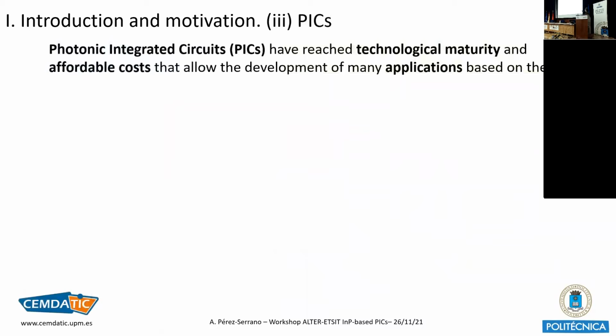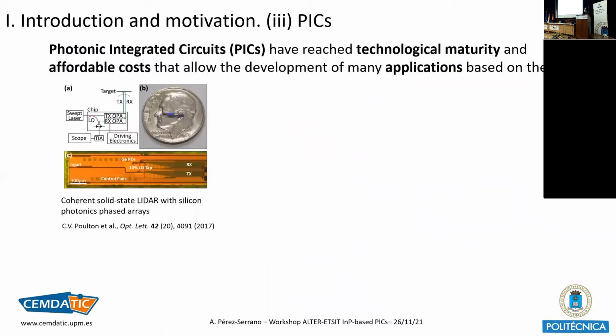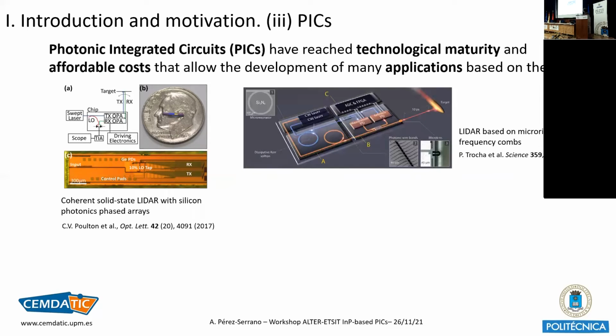Why? Because photonic integrated circuits have now reached technological maturity and affordable cost, and they allow the development of many applications based on them. In particular, in the case of lidar systems, some advances have been reported in recent years. For example, this one is a coherent solid-state lidar with silicon photonic phased arrays, or this one is a lidar based on microring resonators and frequency combs.